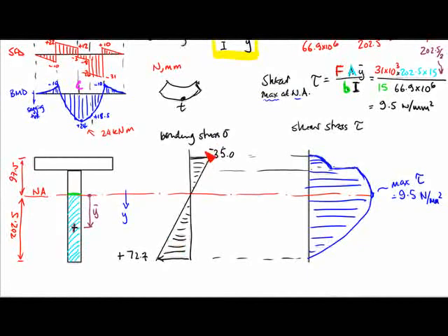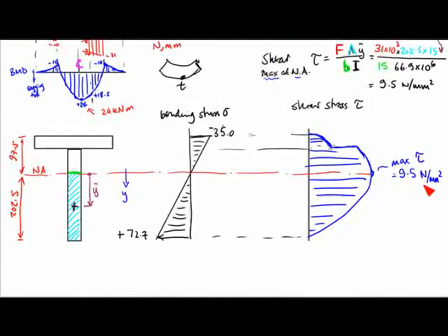So as you can see, the shear stress value is not so easy to obtain as the bending, because with the bending you just simply find the two maximums and join them up with a straight line, and you know that the bending stress distribution is like that. But because the shear stress is parabolic, it's less easy to find, and because the shear stress typically is not as big and therefore not as important as the bending stress, we are less inclined to do the hard work to find out the value, and we fairly often just go for an approximate.